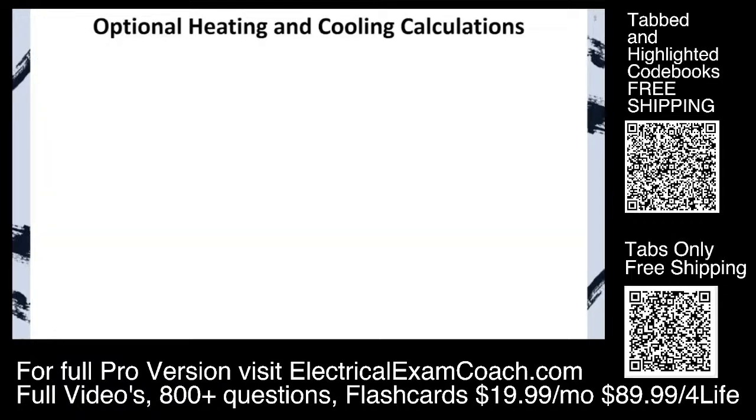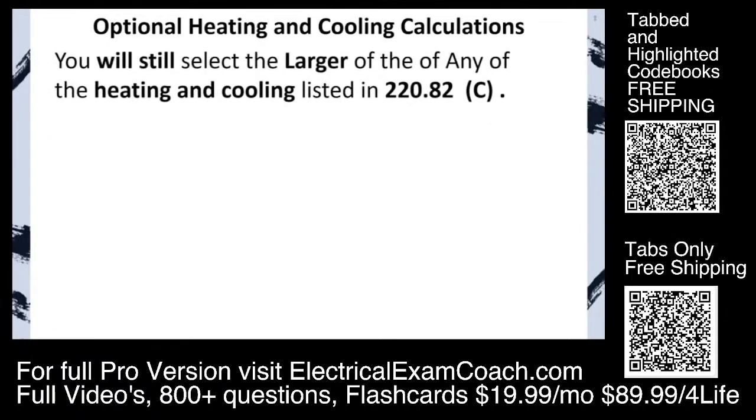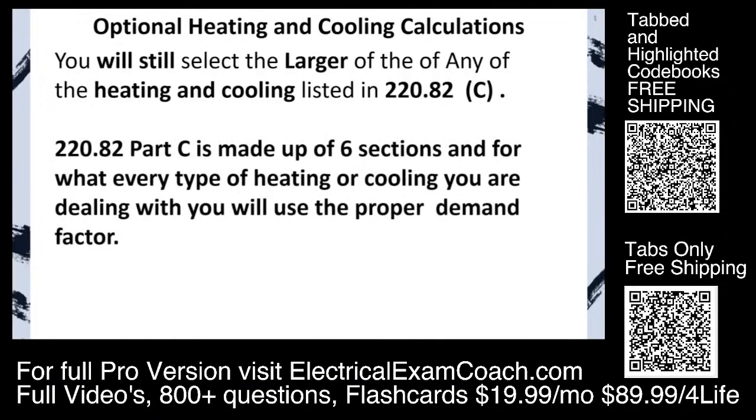With the heating and cooling optional method, we still will choose the larger of any 2 of the heating and cooling listed in 220.82(C). It's very simple. If you get an optional method whole house or an optional method heating or cooling, you just go down and read the prescription for each part. There are 6 different parts. It tells you what to do. It's very simple and easy to understand. And then once you've calculated the heating and the cooling, you just select the larger of the 2.